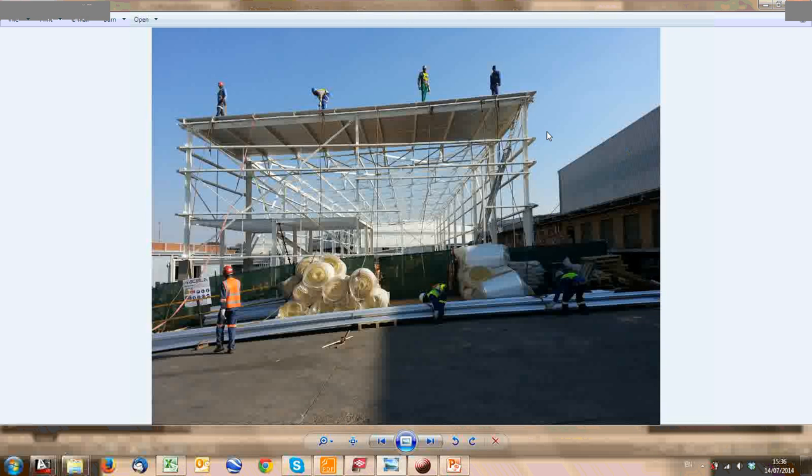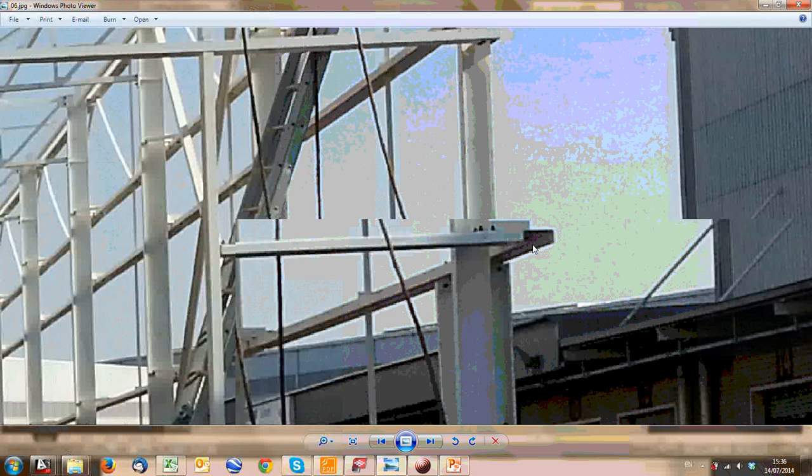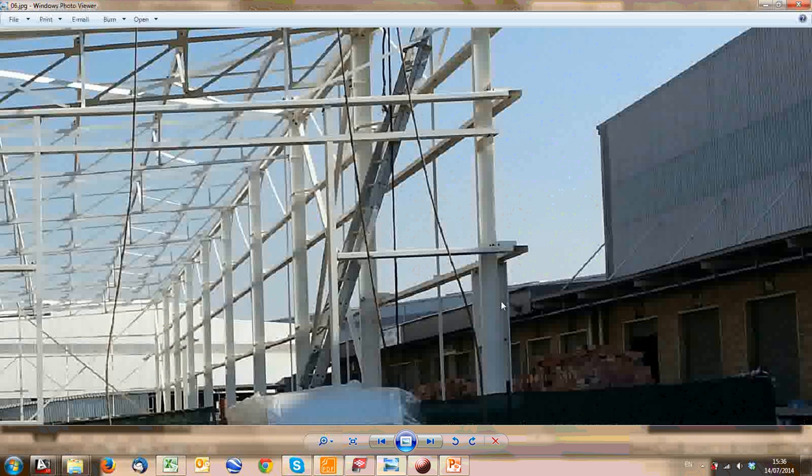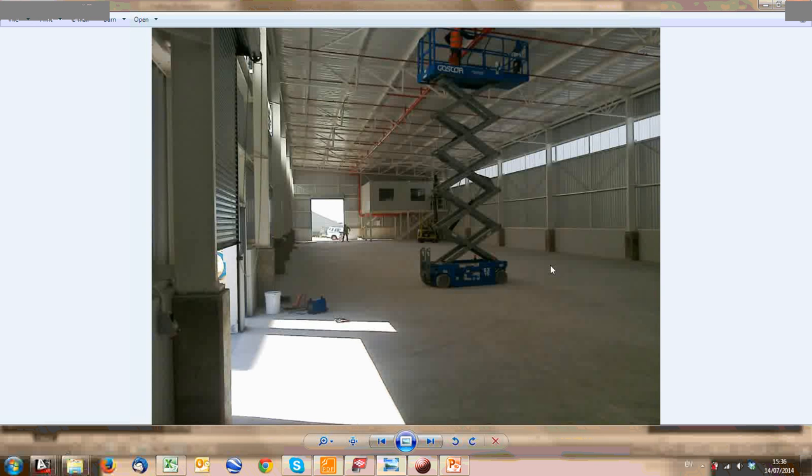And your sheeting line in this picture would be from the center of that column to the outside face of that girt. And that's what we've got to work out now, to know that in the beginning, such that you can set out your building and everything ties together.